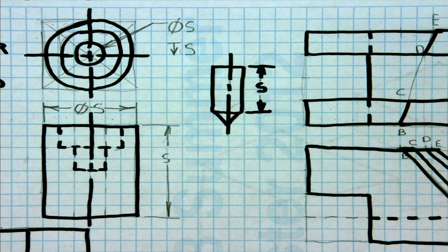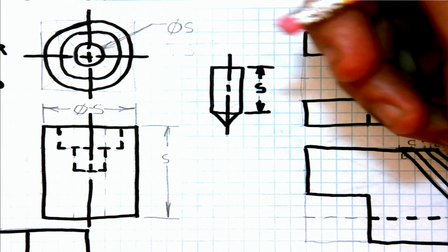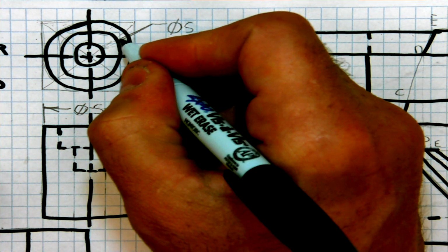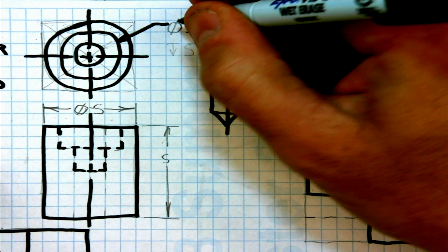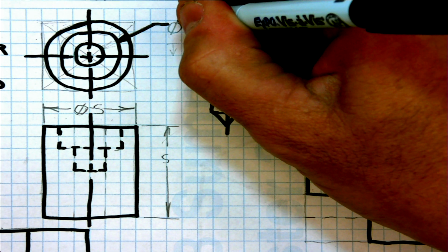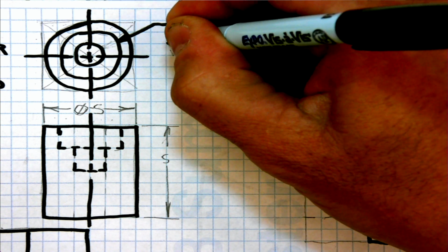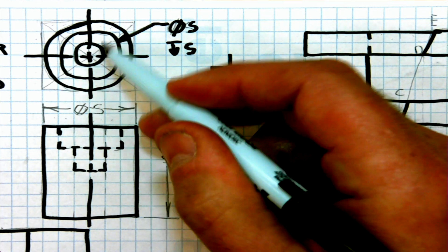Okay, but now we have to tell somebody the sizing of the hole. So now I'm going to move this one up just a shade here, erase this thing off. And now I'm going to point this to the outside since I've made this here. So I'm going to go over here, bring that over, point it to this one, the first counterbore one. So now what we're saying is the smallest hole, the tap or the pilot hole, is a diameter of size. It has a depth of size. So again, that's a small one right in here.